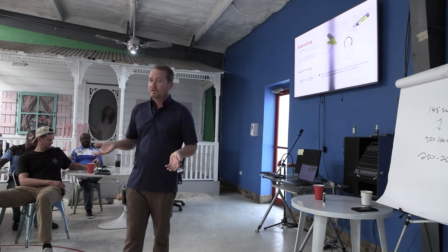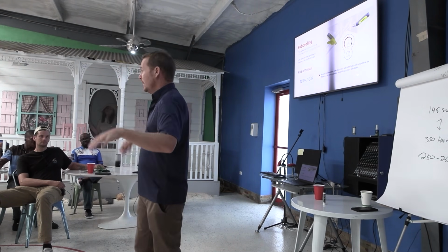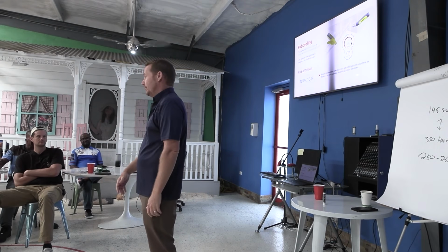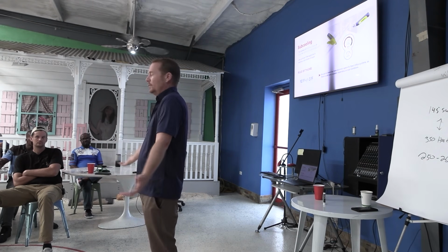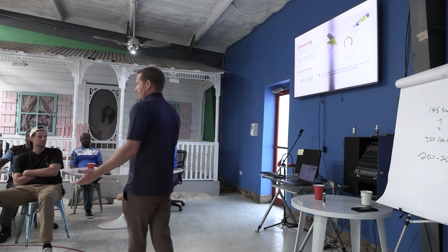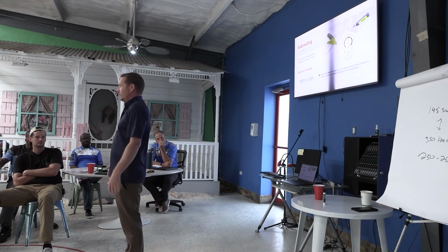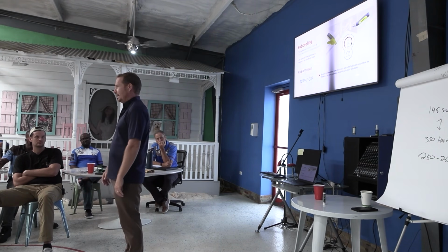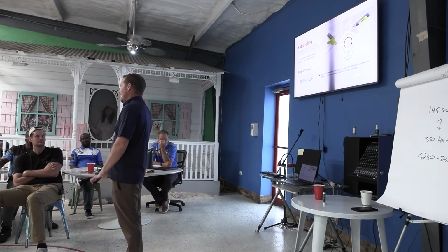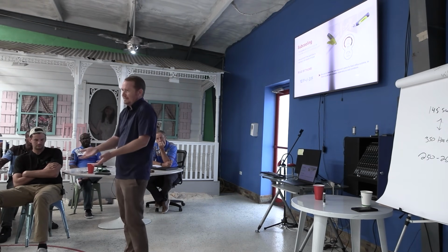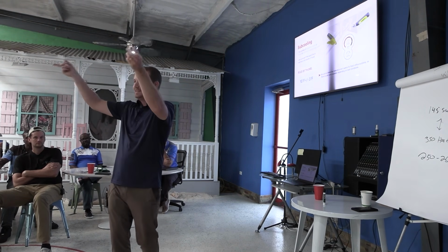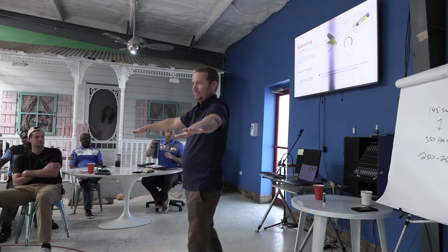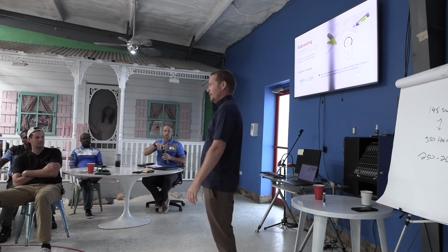If you walk up to a 410A system, you hook up, the thing's off, and you're reading 80 PSI suction and liquid, well, it's got no liquid in it whatsoever. It's at vapor pressure at that point, meaning you have no liquid. Well, yeah, it's flat, so sure, that means something. But other than that, static pressure doesn't tell you anything. When I say static pressure, standing pressure, system is off, your refrigerant pressures tell you nothing at that point. Good point, good question.